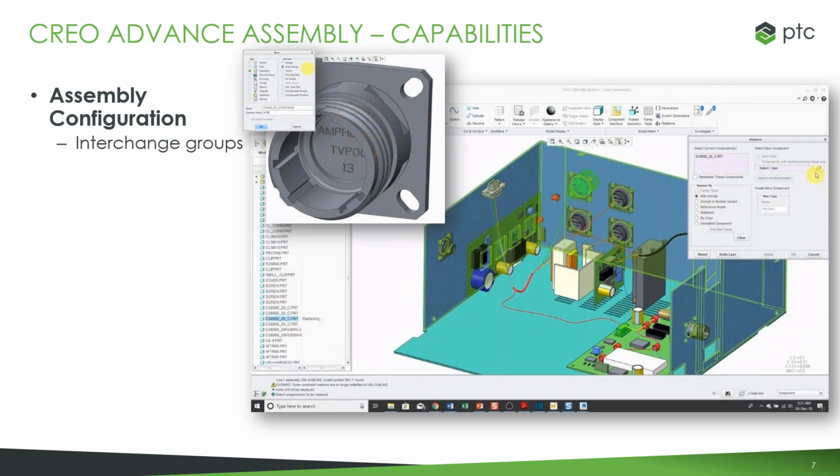So whether that's defining reference tags to automate the assembly, define configuration rules, enable reference forwarding, all these tools allow you to quickly support that interchange group, as well as design to order. So change things up based on what the customer orders. Define simple programs to automate product line customization, leveraging input parameters. Also, you drive the creation of a configurable product from a spreadsheet, layout tables, or programs.